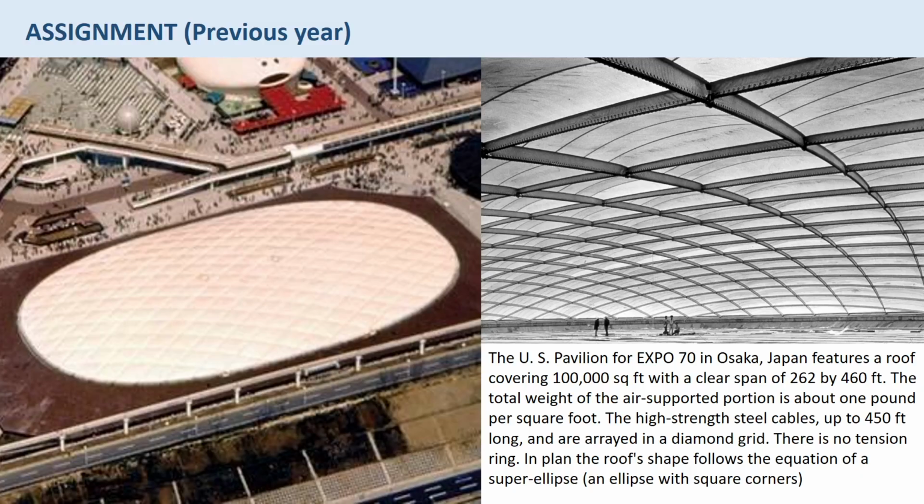Inflatable pneumatic structure: supporting frames consist of air under high pressure. Internal pressure of the building remains at atmospheric pressure. There is no restriction in number and size of openings. They have potential to support an attached structure. So basically in an air supported pneumatic structure there is just one layer, and the pressure inside the structure is higher than atmospheric pressure.